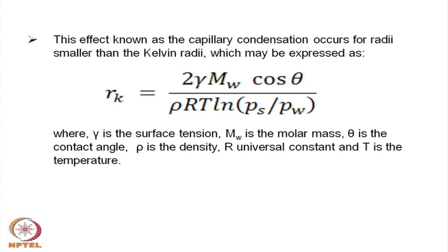Okay. So, we have discussed various types of gas sensors based on ceramic materials, based on whether it is a reducing gas or a combustible gas. In fact, I forgot to mention that the LPG sensors have been used in practice quite extensively based on tin dioxide sensors. So, tin dioxide sensors have been used quite extensively to measure the combustible gases, including the cooking gas. So, gas leakages can be determined by this.